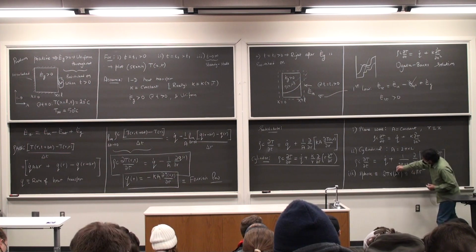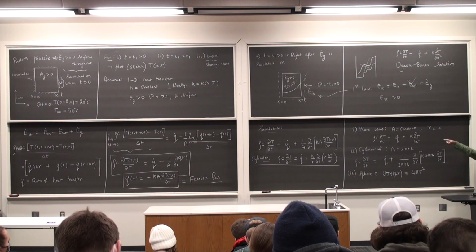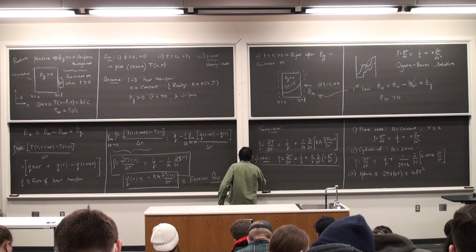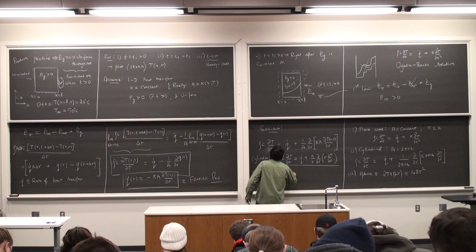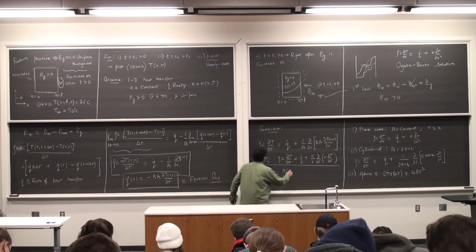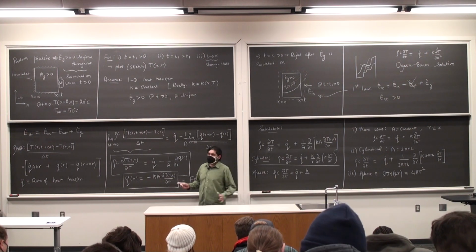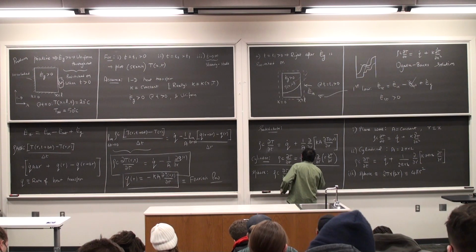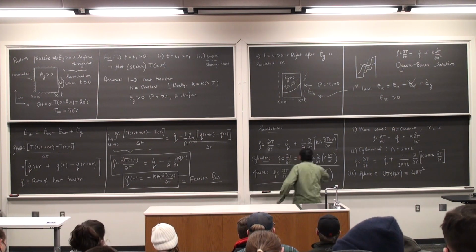So this is the number 2 here. So 4 pi r square. If you do the substitution into the main heat diffusion equation that we have derived, not going to do that, you'll get the following. Rho c dT by dt is q dot plus, assuming constant thermal conductivity, k by r square d by dr of r square dT by dr.